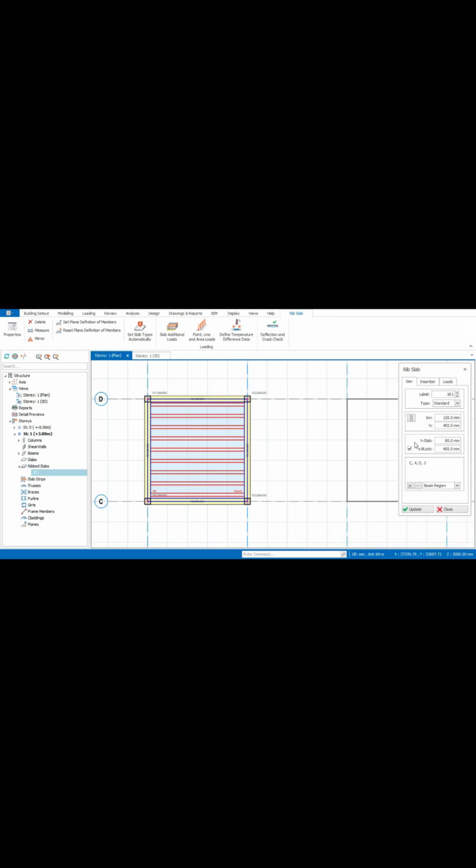And you can get that by going to your measure. You can use your measure button to get that. You can see that this S block is 400 here. And when you measure this, you see that it's 400. You can press escape. Then the BW, which is the width of the rib beam, can also be identified like this. As you can see, it says 150.